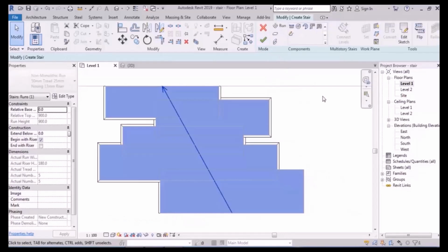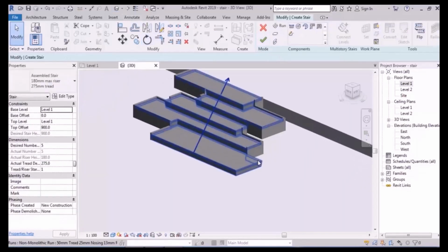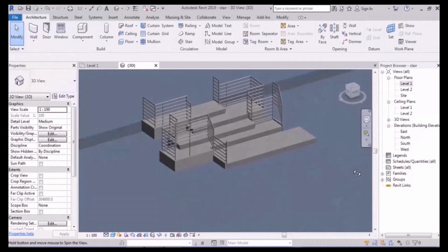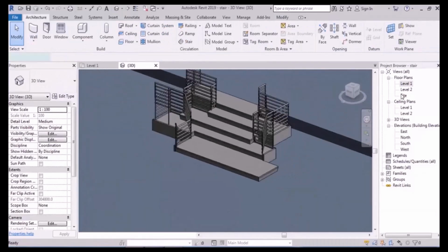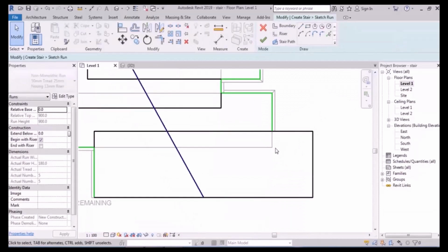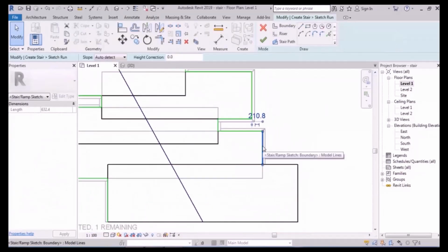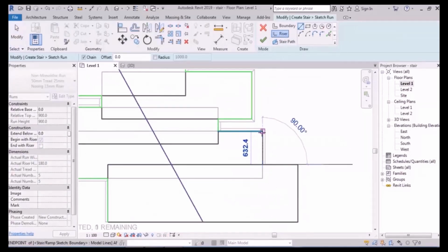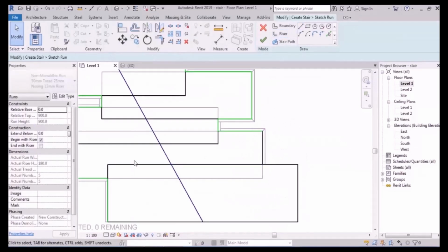But what is the difference? We enter the staircase from here. This part will not have railings anymore. Now, next question. Can we remove this one and have the boundary until here too? No, not anymore. Because if we draw a riser here, this riser will not be connected to the boundary. And this part here now is not correct, right? It's wrong.